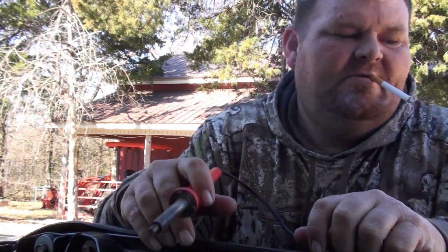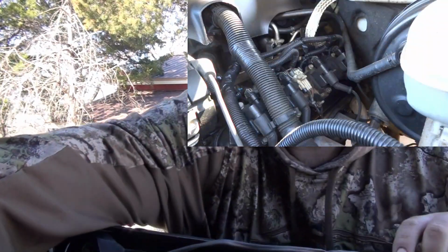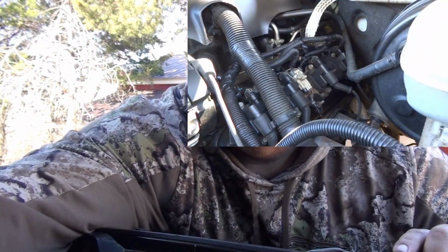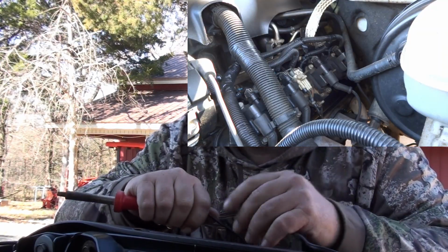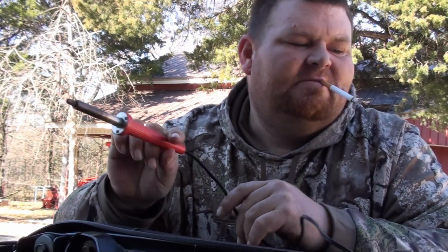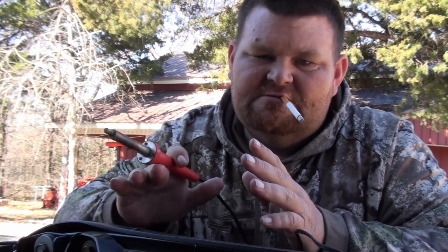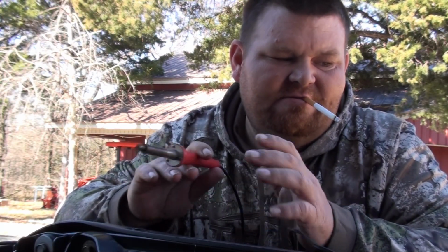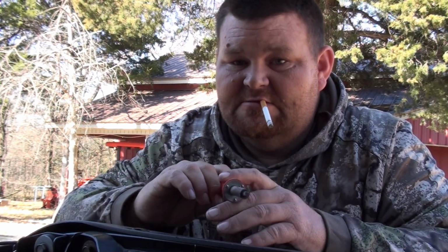So your spark timing table is the timing of when the spark plug is firing in correlation to when the piston is coming up or down in the cylinder. Too early, you get spark knock. Too late, you lose power. The ECU uses load and RPM to determine how much timing to give. High load needs less timing and a light load needs more timing. Timing is the engine's power curve, but only if your tune is safe and everything else is good to go.